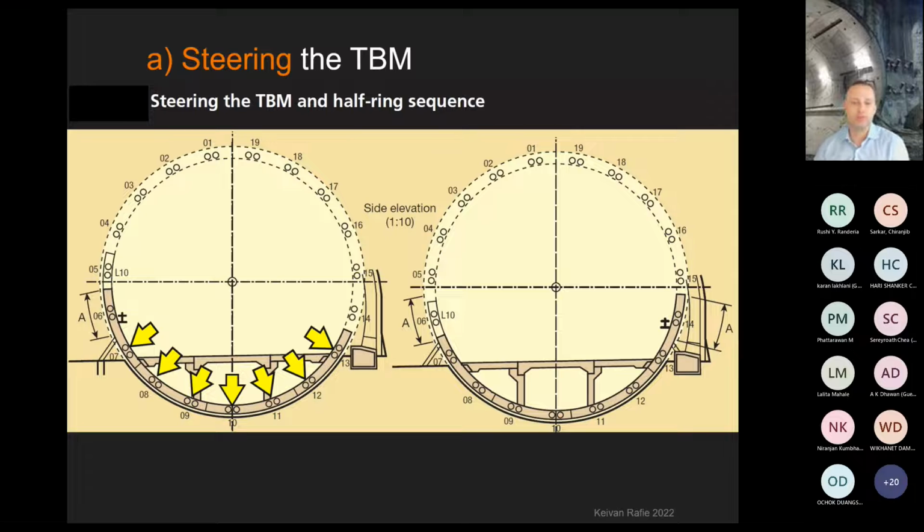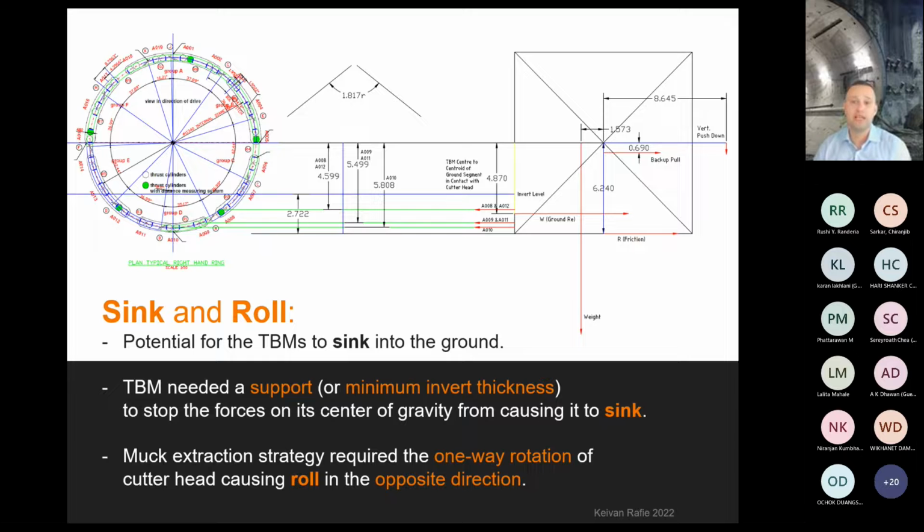As you know, normal TBM operation involves working with the TBM rams in groups. So we had to work with Heron Connect electricians to modify the TBM software to say which rams exactly we want to push, and then group them separately to the left or right so we can navigate.